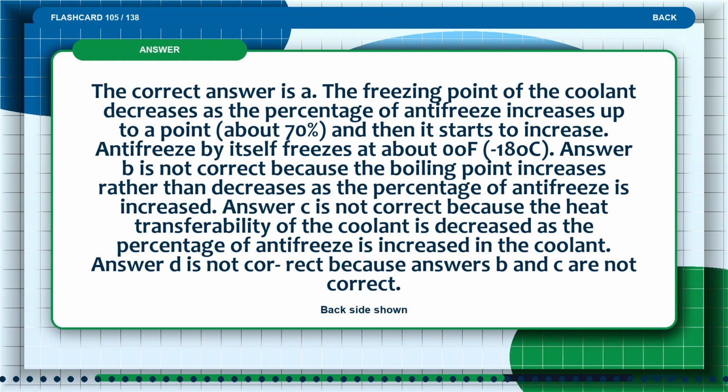The correct answer is A. The freezing point of the coolant decreases as the percentage of antifreeze increases up to a point, about 70%, and then it starts to increase. Antifreeze by itself freezes at about 0°C. Answer B is not correct because the boiling point increases rather than decreases as the percentage of antifreeze is increased. Answer C is not correct because the heat transferability of the coolant is decreased as the percentage of antifreeze is increased in the coolant. Answer D is not correct because answers B and C are not correct.